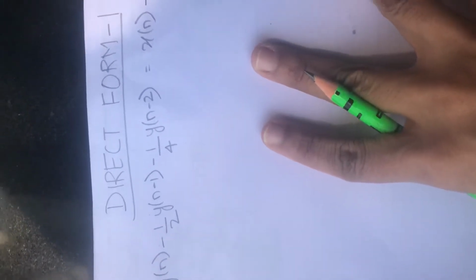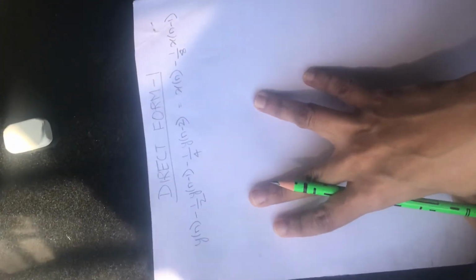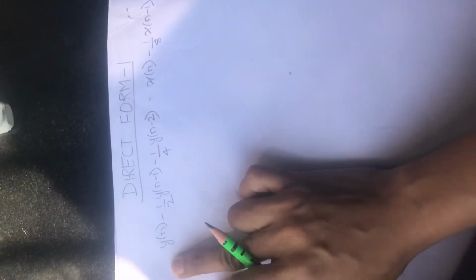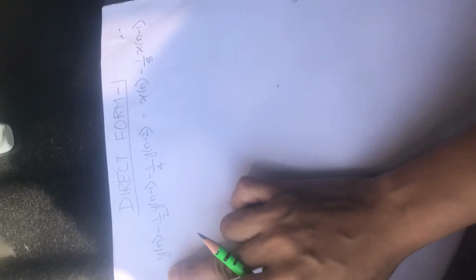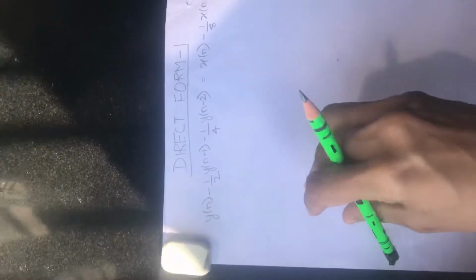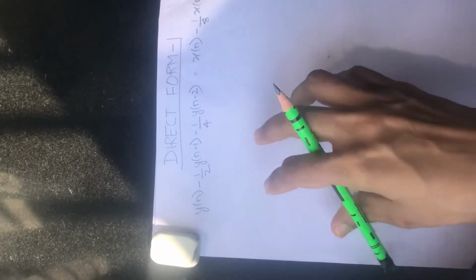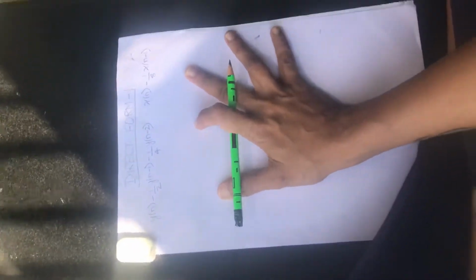Today's video is based on system realization. In Z transform, we know how a system is formed, that is the H of Z, and how we derive an H of Z from the given difference equation. Now, in this section, we learn how to realize, or how to convert an on-paper system to an actual practical implementation, making use of certain hardware blocks such as adders and delay elements.